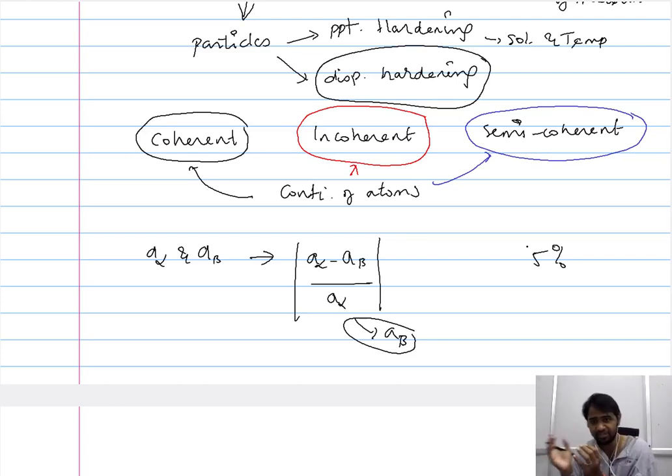The range of different interfaces varies. So this is one of the common threads that you can find, that when the difference in the interplanar distance is close to 5%, it is not more than 5%, it is close to 5%. So the thing is that there are no definite ranges. Of course, there are definite ranges for the extreme limits, and for the limits in between, but for coherent it is just stated that the difference should be small.